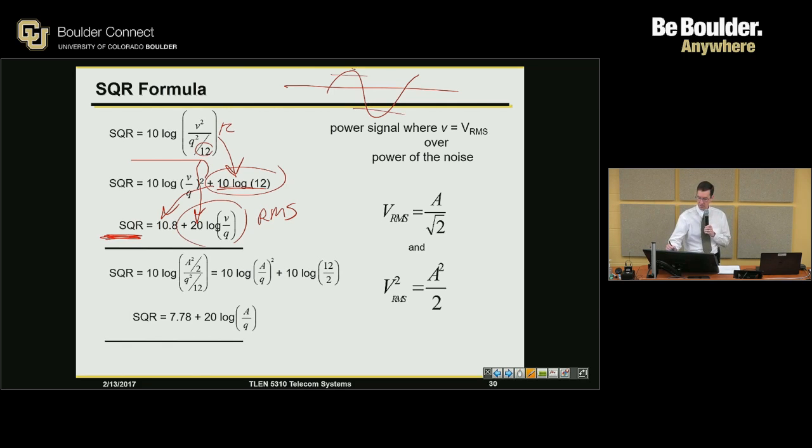This peak up here and this line there, that's a difference of 3 dB. So basically the difference between the peak voltage and the root mean squared voltage is essentially 3 dB, or another way to put it is it's putting square root of 2 in the denominator.